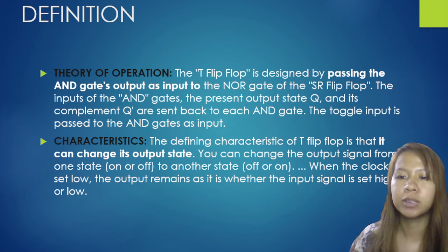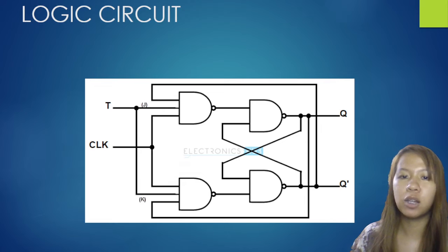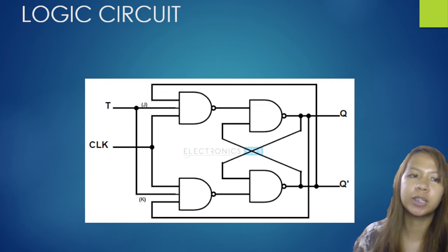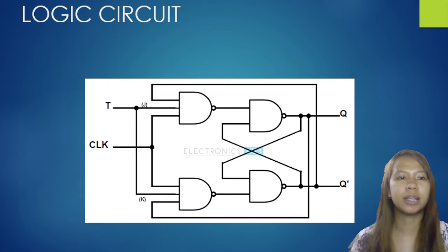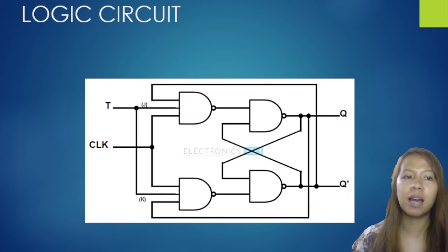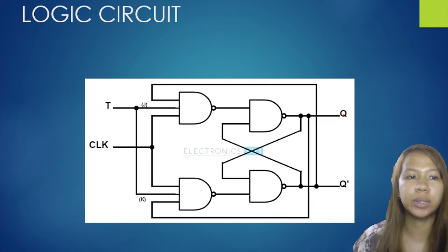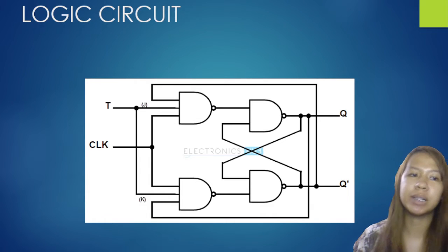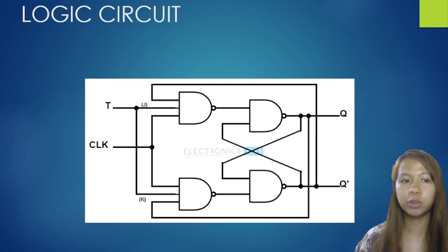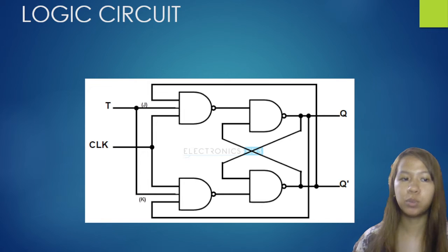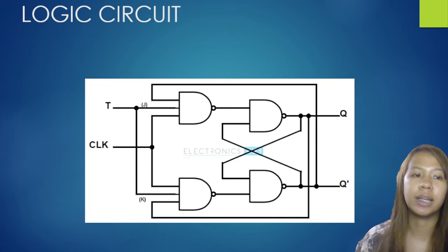In the logic circuit, a gated latch is a useful component, but the output can change whenever an enable signal is high. It introduces a lack of precision and reliability into whatever digital interface is built around the latch. It would be better if the latch responded to input changes only at a specific moment in time. The trouble is, once we have implemented this functionality, the latch is no longer a latch, it's a flip-flop.